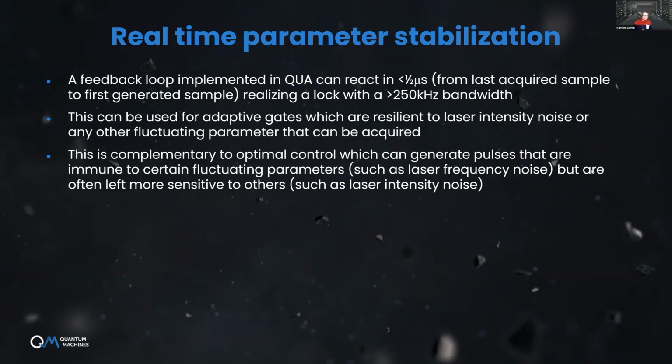What I will show you in a moment is a PID lock loop. There, all the calculation of the proportional, the integral, the differential error, and applying all that, takes about an additional 150 nanoseconds. So the total latency is 350 nanoseconds, and that is comparable to a lock bandwidth of more than 300 kilohertz. And this is very important.